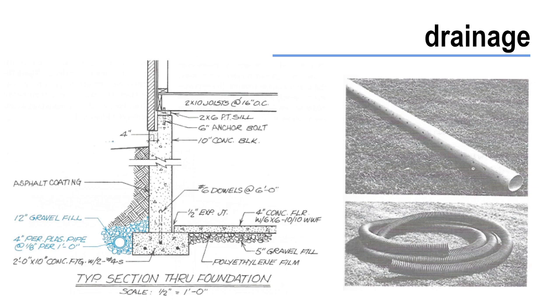When we have our footing drain included in a drawing, we show it in the section view detail, and that's what's occurring right over here. In our practice from the section view lecture, we had that pipe running in here with our gravel surrounding it, so that water can infiltrate into the pipe and then disperse outside.